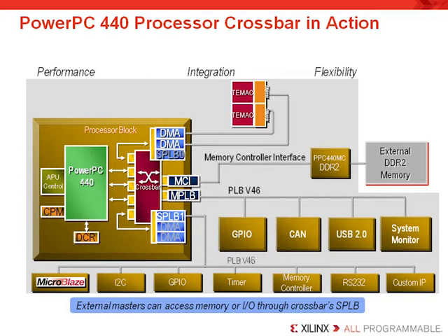But the PowerPC cannot gain access to any of the peripherals attached to the slave PLB bus because this connection cannot be made by the crossbar. This is a simple multiprocessing system and illustrates the use of the slave PLB interface, showing that it allows multi-ported access to the memory and I/O of the PowerPC 440 processor block.